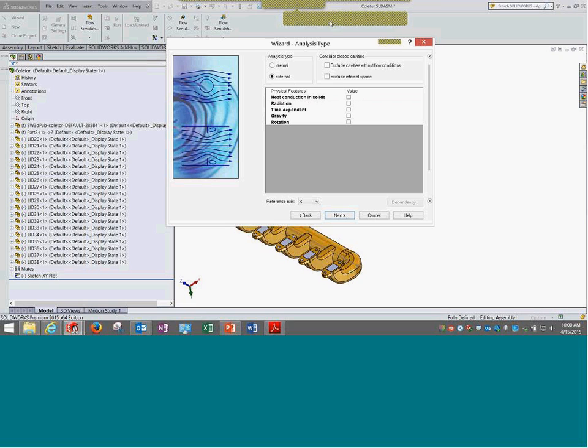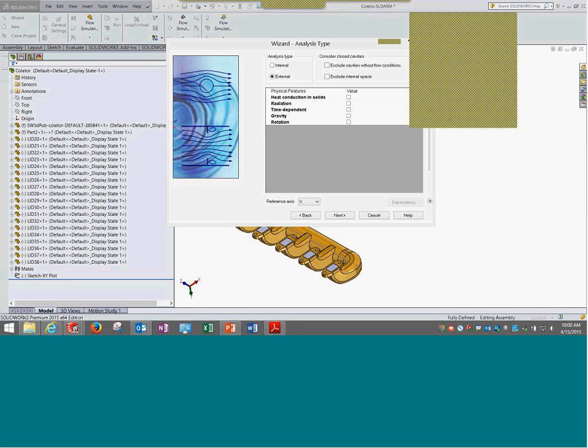Any other questions? Yeah, my question is: what does the display show in results in the cavity without flow? No results are displayed. Yes, you're right, there would not be any results displayed over there. It would be treated as a solid geometry.